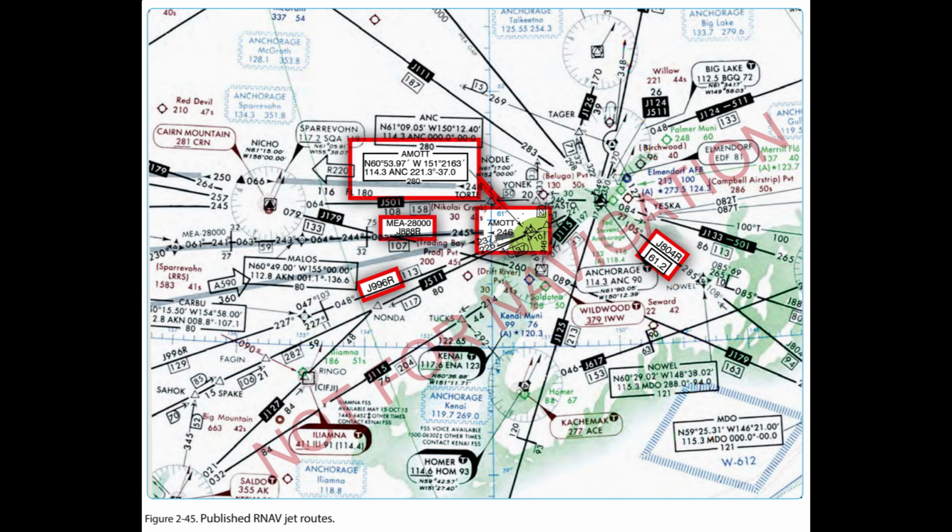5. Define the route of flight after the departure fix, including each intermediate fix, turn point, and the arrival fix for the destination airport in terms of latitude/longitude coordinates plotted to the nearest minute or in terms of Navigation Reference System (NRS) waypoints. For latitude/longitude filing, the arrival fix must be identified by both the latitude/longitude coordinates and a fix identifier as shown in the example below.